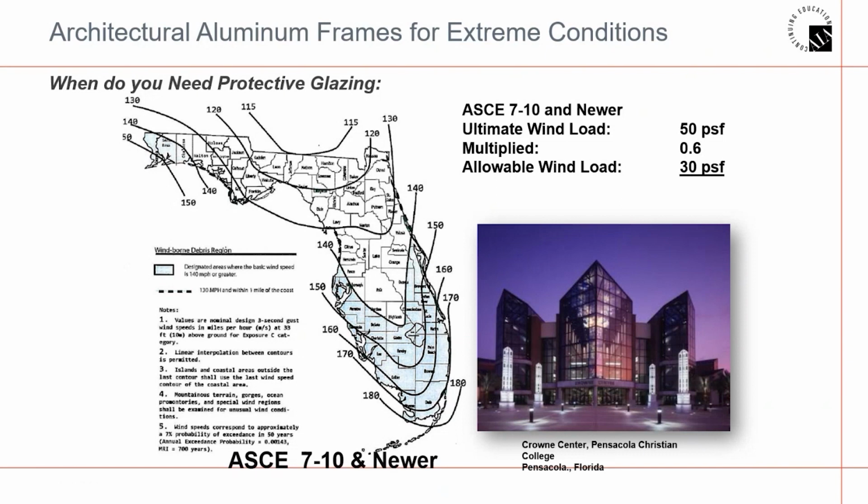If the ultimate wind load has been specified for a fairly typical inland commercial building, do question if that's what they need, or can it be factored by 0.6 to the allowable wind load. In most cases, most commercial buildings are using allowable stress design, but just make certain of that on your project.